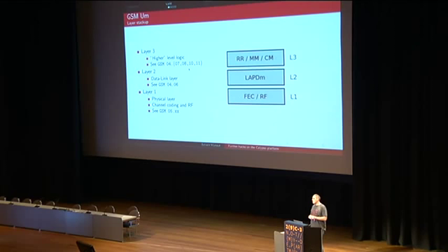It can itself be decomposed in 2 parts. The one I would call the channel coding. So basically, you take layer 2 packets, you add things like forward error correction, convolutional coding, CRC, things you need when you transmit data over the air and you want the data to be actually received clearly. And the second part is the actual RF part. That is, you take the bits and you somehow modulate them and transmit them to whoever you want to transmit them to.